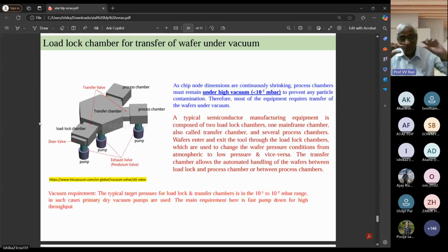So these are monolithic chambers. Central chamber, each sub-chamber has got its own pump. Then between them there are square-looking walls. So these walls, one is a load lock. Your silicon wafer will come to the first chamber, on the left side, towards my side. It enters there. At that time, that wall is closed. The central transfer chamber is isolated. After that, we evacuate, seal, clean, then make it enter into the next chamber.